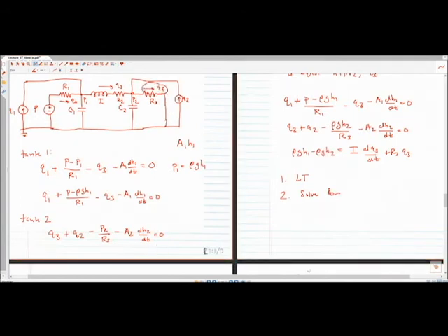Okay, so if you notice, nothing here is in terms of QF, right? But we do have a variable that is statically related to QF, and that is the flow rate through this last resistor, which is equal to the pressure drop across the resistor over its resistance value. So we have a static relationship. We have that P2 is equal to R3 QF, right? And so solving for P2 is just as good as solving for QF, because then all you have to do is divide by R3, and then you have your answer. Step 2 is going to be solve for P2 or H2, because those are also statically related, given by rho G. And then the last one is going to be to compute P2, compute QF, which is just multiplying by a certain constant to do so.